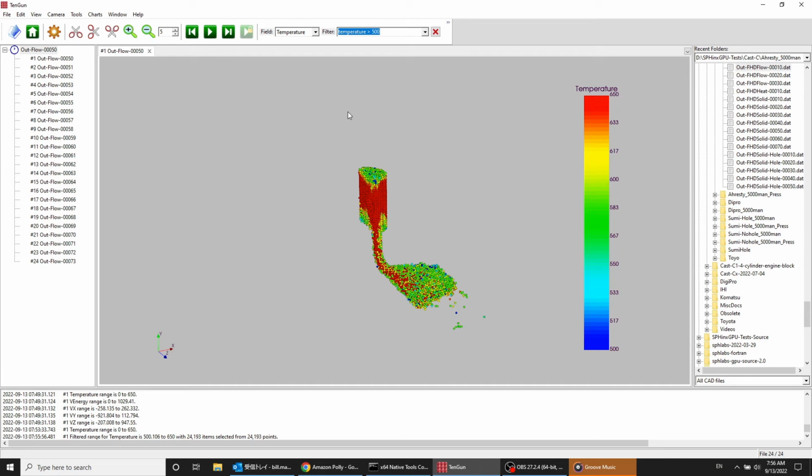Finally, one more point for this segment. Notice the camera menu item. This is used to position the view camera to one of 6 locations around a viewing cube. You can sometimes rotate the model with the mouse, but oftentimes this is easier. You can also use keyboard shortcuts, and I most frequently use Ctrl-F for the front view, Ctrl-L for the left view, and Ctrl-R for the right view.